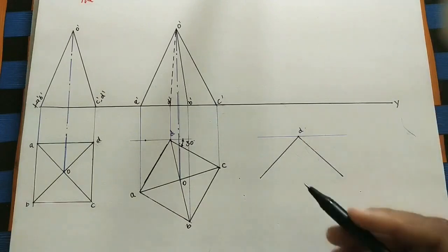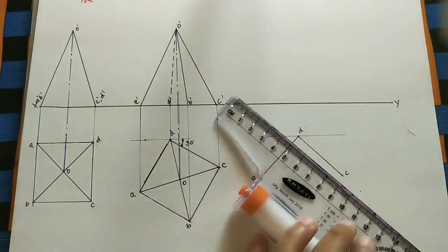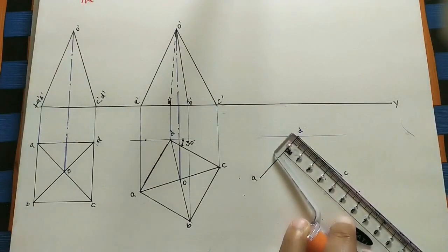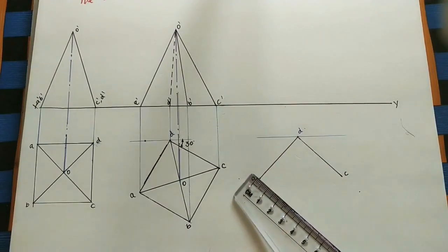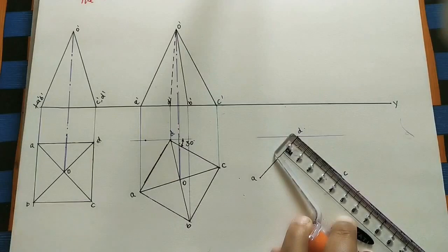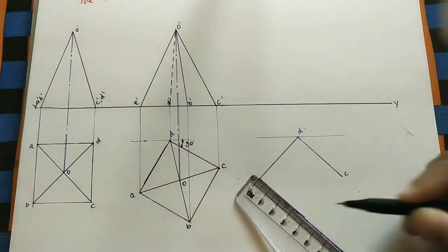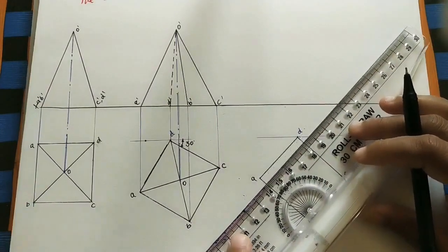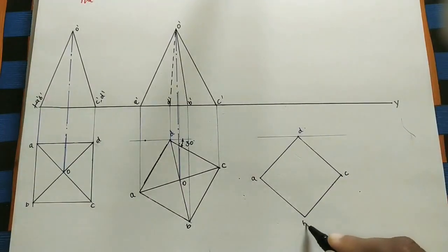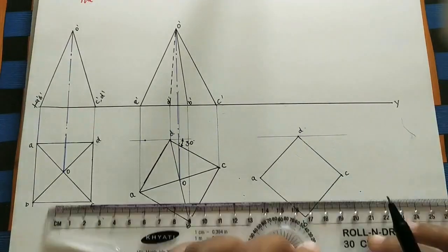Now here mark the corners. D here we have marked, here A, here this point is C. Okay, do the parallel lines at the other sides also of 4 centimeter. Take a 4 centimeter parallel line here. And take this as reference. Do one line here, parallel line. Okay. Mark this corner, it is B. So B and D should come on the same line. After that, mark the apex. For marking the apex, join opposite ends.